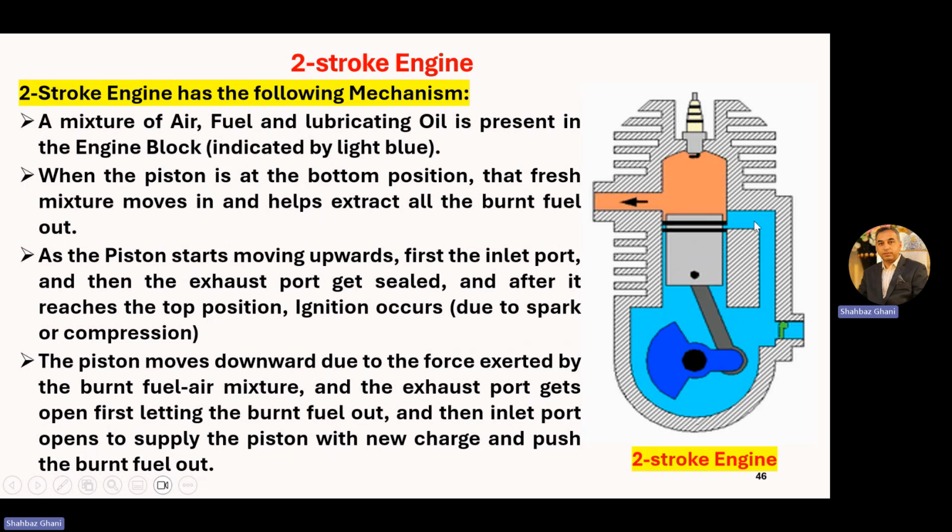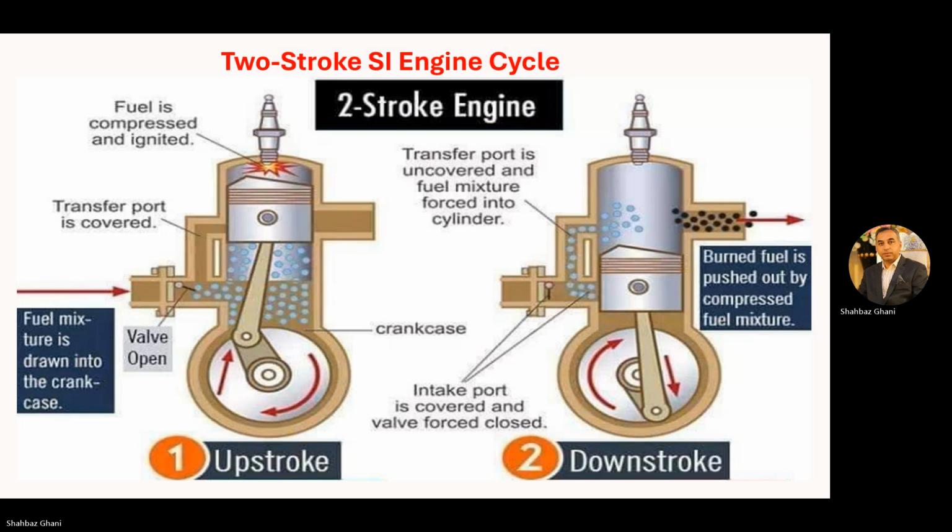The fresh air fuel mixture comes in and it also forces the exhaust gases outward. Same, but here the piston top is different. This is to give swirl action.